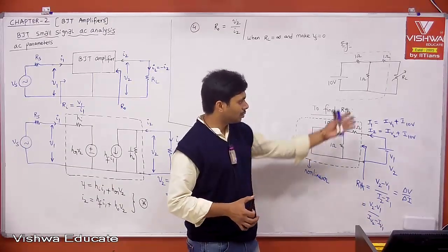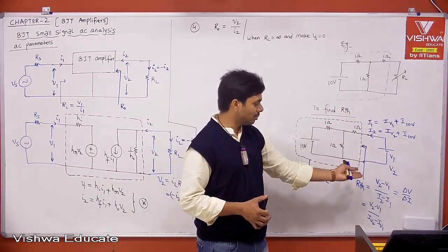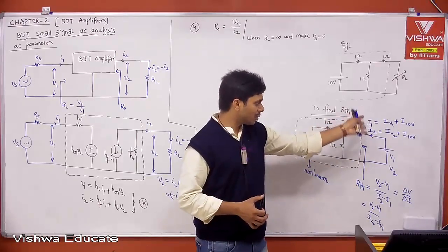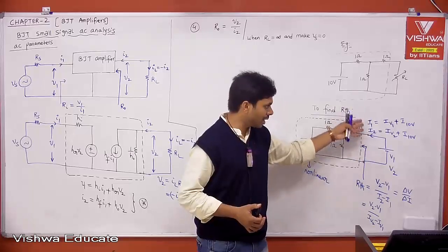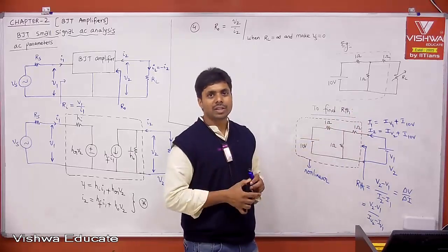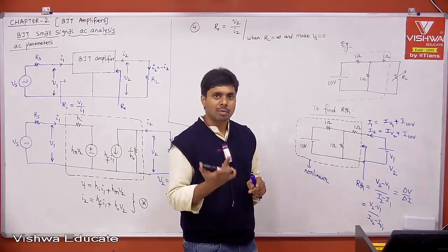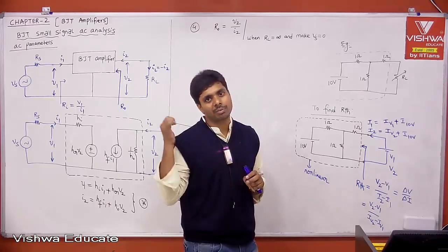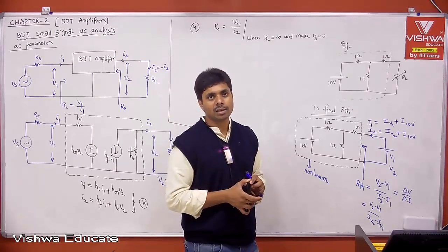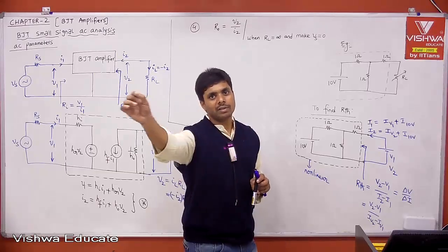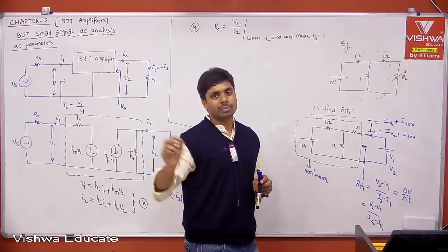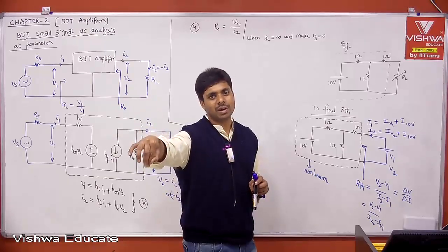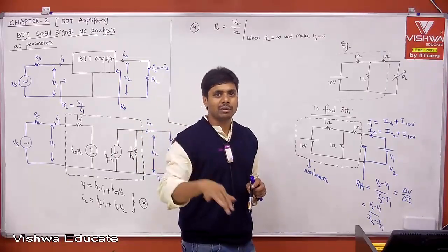And why are we going with the dynamic resistance? To cancel out the common quantity in the output currents. Then we go with the dynamic definition like V1, V2, I1, I2. I told you that BJT is non-linear, MOSFET is non-linear. That's why I already gave you the summary before starting our BJT small signal AC analysis: ID1 because of VGS1, ID2 because of VGS2, ID2 minus ID1 because of VGS2 minus VGS1. If there is any common quantity, that will be cancelled.